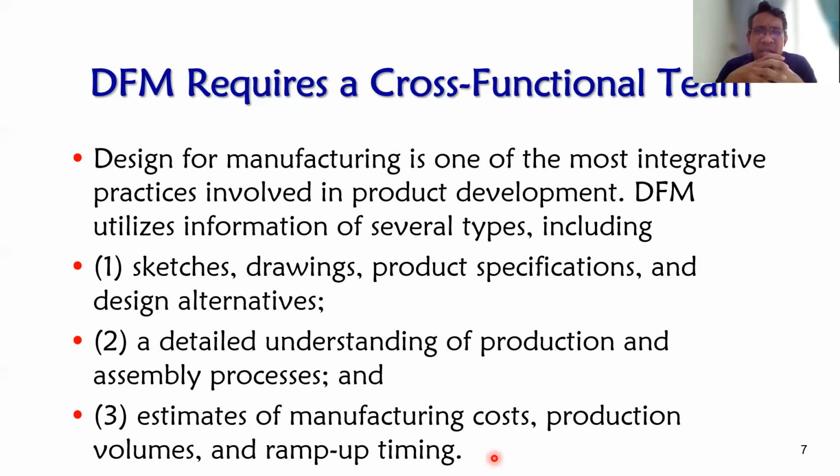For example, they design the tolerance. The tolerance itself, they need to know how to achieve it. For example, the designer cannot design with a tight tolerance. If they do that, the manufacturing doesn't have the capability to produce. So they need to buy another tool.